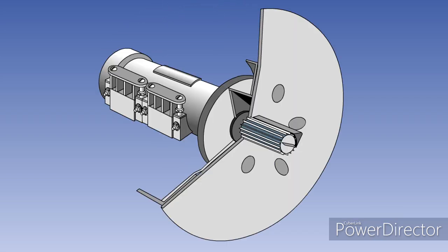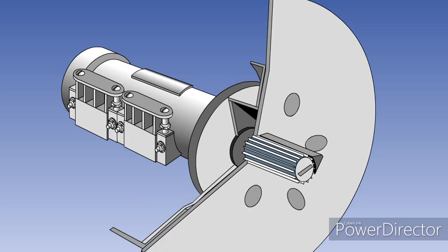The English Electric or Napier ice detector is a mechanically operated accretion type of detector. In this detector, a serrated rotor shaft is continuously driven by an electric motor. The shaft rotates adjacent to a fixed knife-edge cutter, with a clearance between them of less than 0.02 of an inch. The unit is mounted on flexible mountings on the side of the aircraft fuselage, with the rotor shaft protruding into the airflow, with its axis at right angles to the airflow. The cutter is in the lee of the shaft.